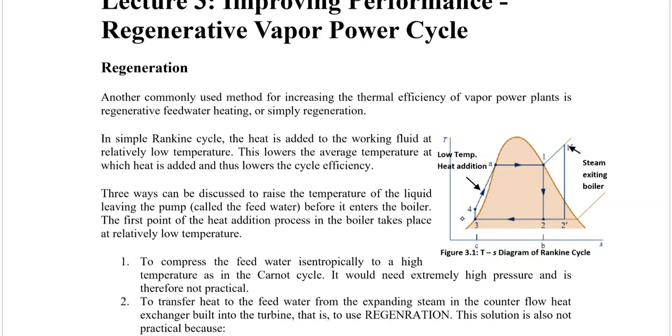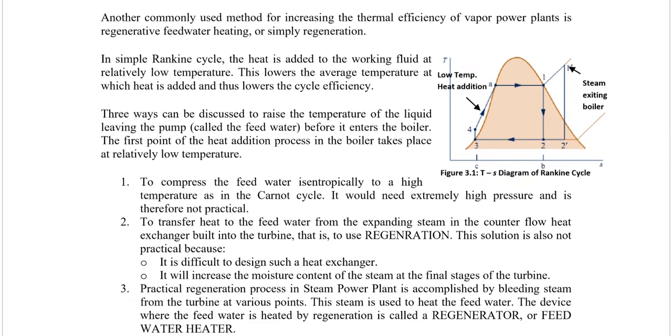There's another method. If you can imagine, the maximum amount of heat which is expended is in a steam turbine. That's the maximum amount of enthalpy which is expended in the steam turbine. So we are expanding from H1 to H2, and this is the maximum amount of heat which the cycle is losing. So if we can somehow capture or harness this amount of heat from the turbine, and then put this heat into state number 4, then the efficiency of the cycle would increase.